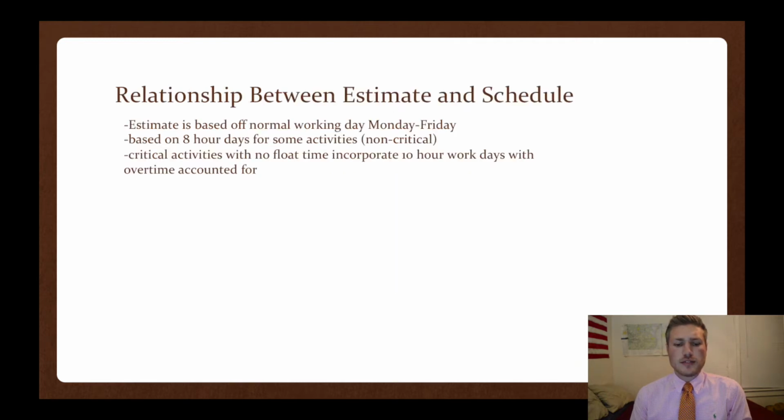When talking about the estimate and the schedule, there's a close relationship between the two. The estimate is based off of normal working days, which means Monday through Friday, and they're based on 8-hour days for non-critical activities, which are also known as float activities. Critical activities with no float time incorporate 10-hour workdays with overtime accounted for.